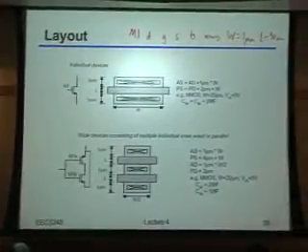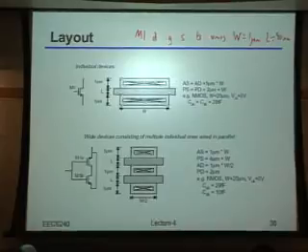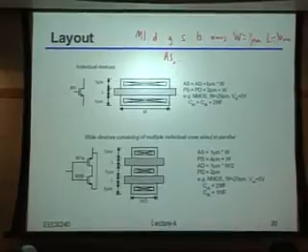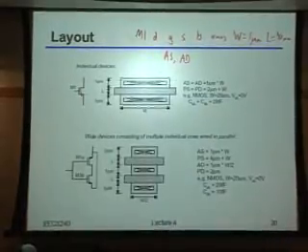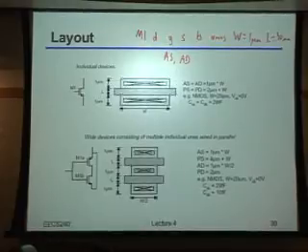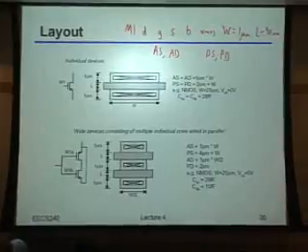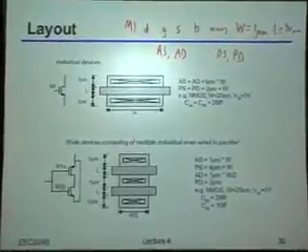In order for it to have a reasonable idea as to what those parasitics really are. So indeed, the way we'll capture that is with these so-called AS, AD, PS, PD parameters. And each of these really just stand for either an area or a perimeter. As you might expect, AS and AD are both areas, AS is the source, AD is the drain. And similarly, PS and PD are essentially the perimeters of those drain or source areas.